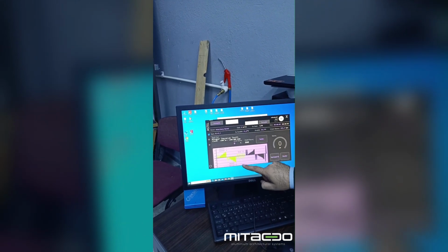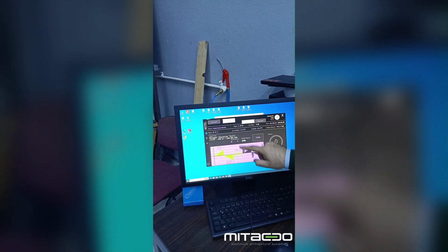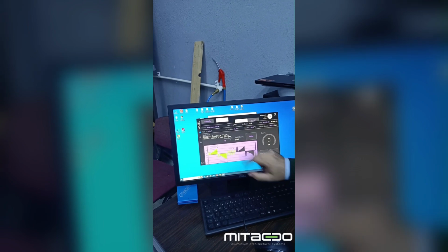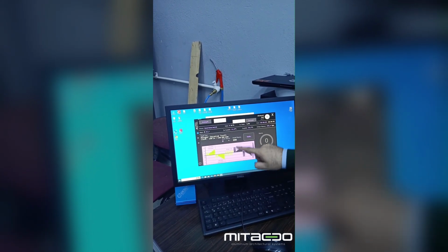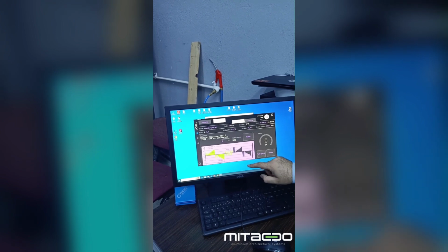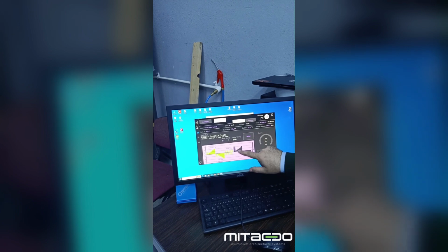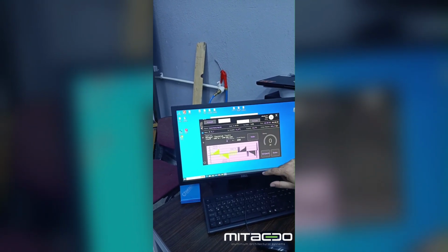The second step was our loop test. It also passed our 50 positive and negative loop tests. After this, we will go back to the beginning of this process and do the air tightness test again, going back to the beginning. First 3 positive impacts, then a positive air tightness test, then 3 negative impacts and a negative air tightness test.